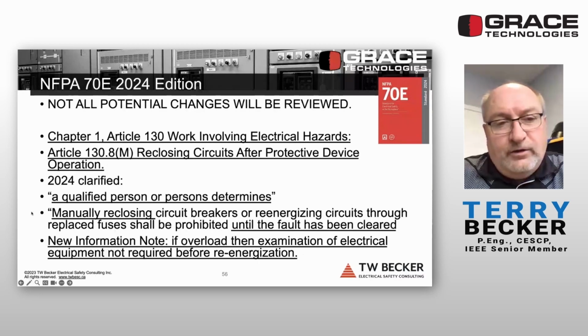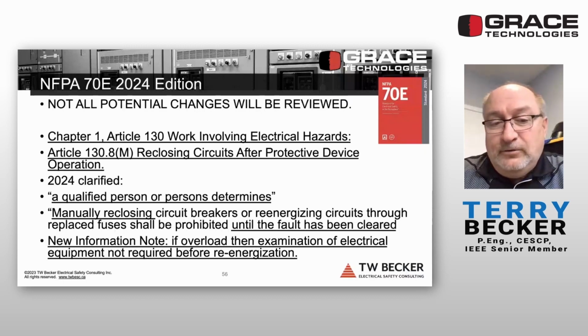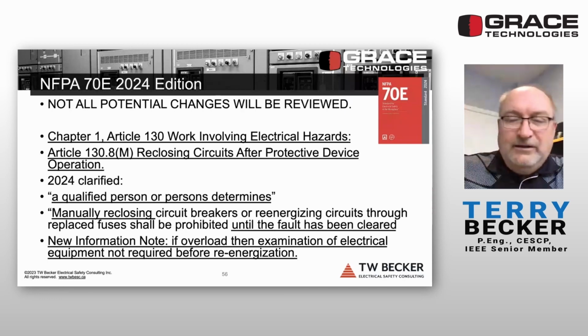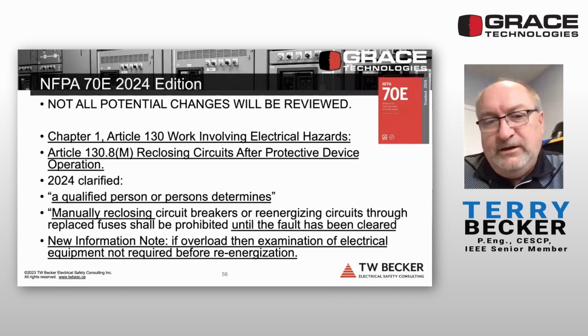So again, Article 130.8, reclosing circuits after protective device operation, it just adds some additional language, which again, only a qualified person should be reclosing circuits, but only after doing a root cause failure analysis. All right, so you should be doing root cause. You shouldn't sit there and continue to reclose, believing that the fault is going to clear, because it won't. There always should have been some root cause failure analysis before even attempting a single reset.